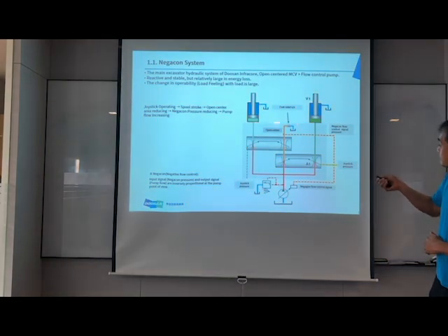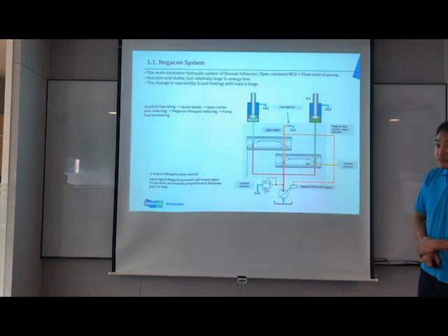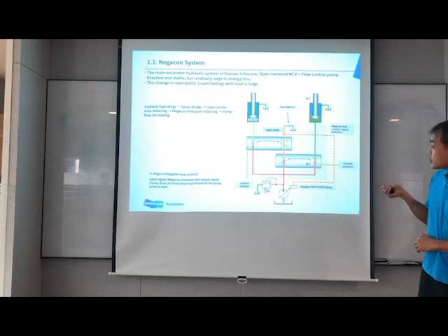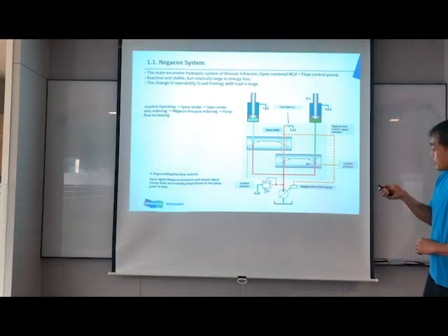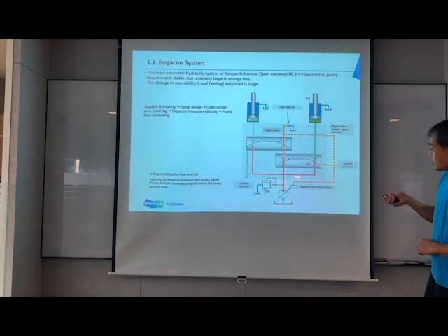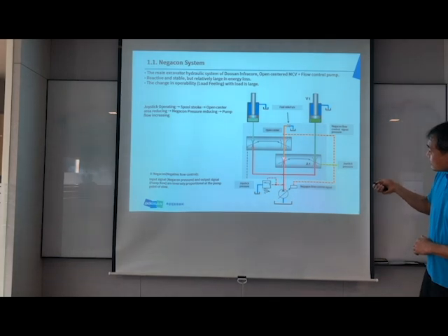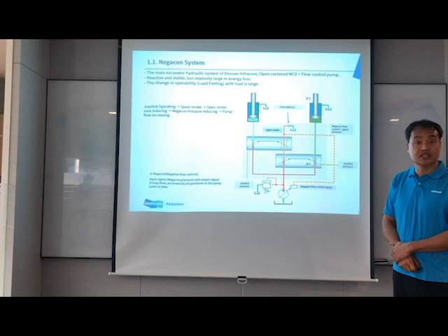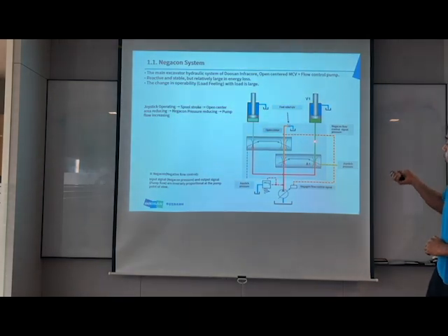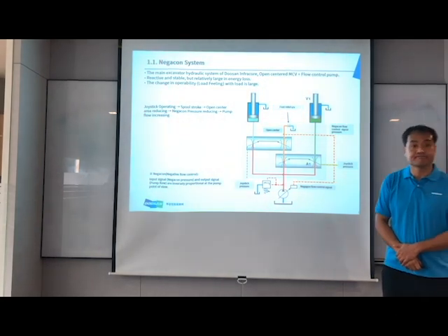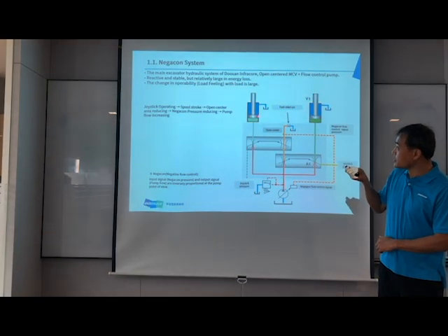And then next, this one, the control valve, right? Basically the control valve. For example, in a no-working condition, what about the spool? The spool is closing this line, so the cylinder doesn't move. But when the operator moves the joystick, the spool shifts, right? At that time, this line should be open, and this line should also open. That's why the cylinder moves. But the center bypass line, because it is the center line, should be slightly closing. So once again, when the spool shifts, this line should be slightly closed and this line should be open. Alright? And then this one, the cylinder, right? When the cylinder gets the flow, the cylinder moves.